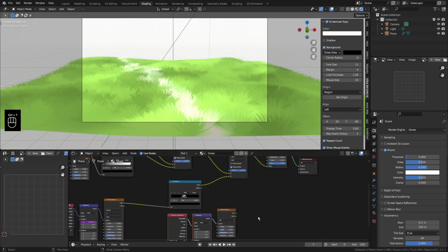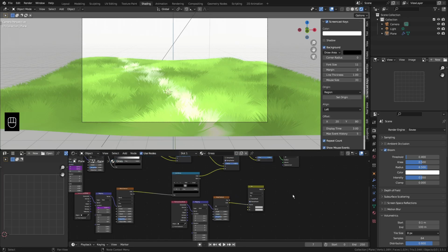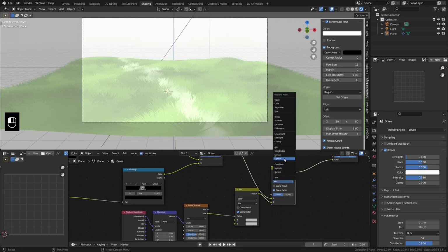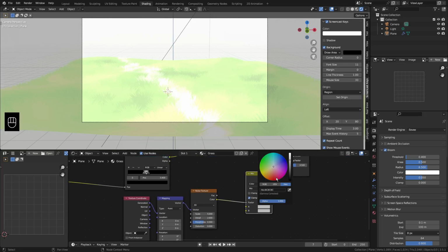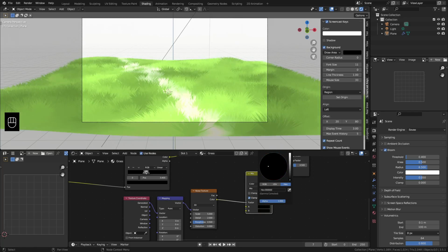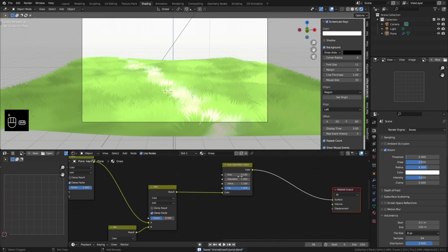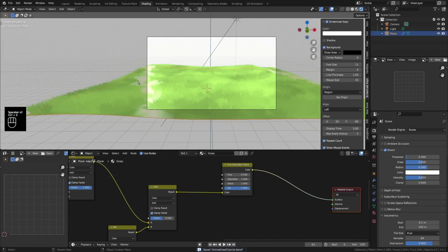Ctrl T. Then let's add a mix here, factor, then mix it here, make this add factor to around 0.5 as of the moment. Now we could change this into our color that we want, so this makes things more smoother. So yes, I think this is already good, and you could change it into a little bit like this. Yeah. Next, what we want to do is to have an animation for the grass here.